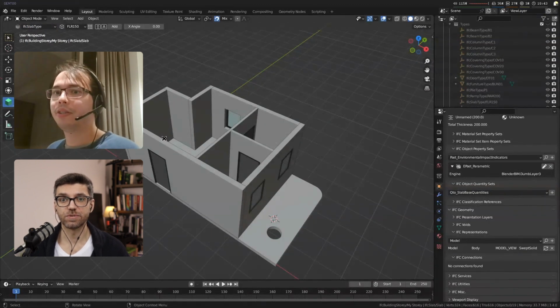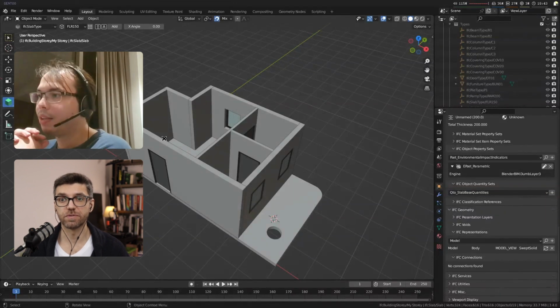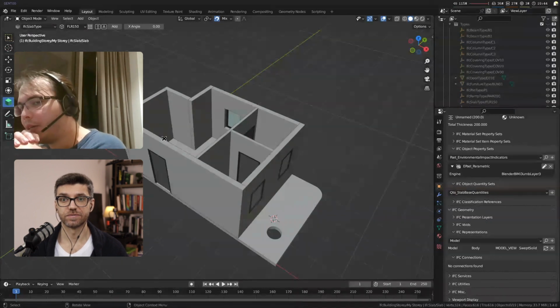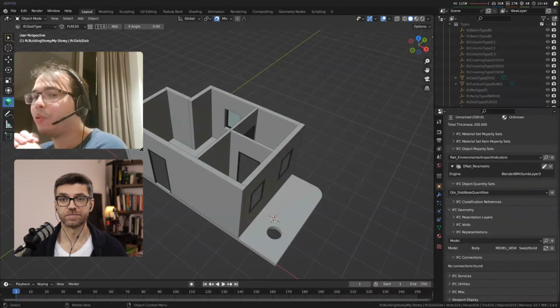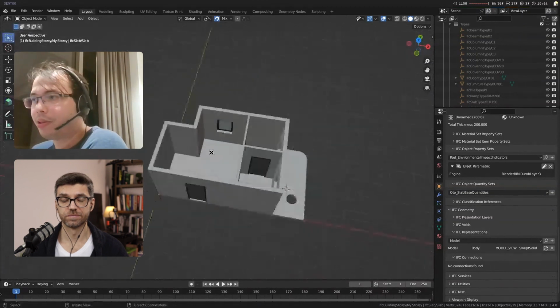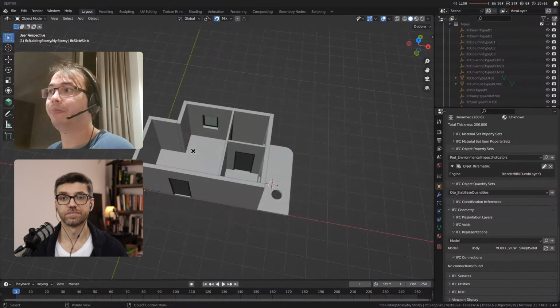Can you define some sort of parametric relationships, let's say, between a wall and the slab? So if you move the wall, they align? At the moment, the slab edge and the wall do not have a parametric relationship, but I can have a wall that extends up towards another object, like a slab or a roof. So that type of parametric relationship does exist.